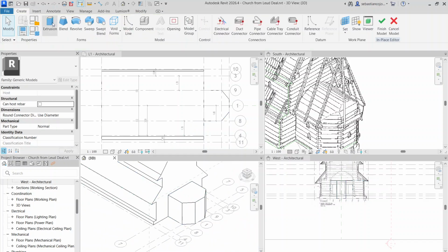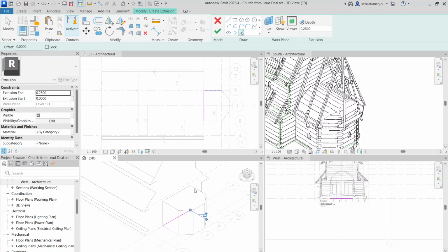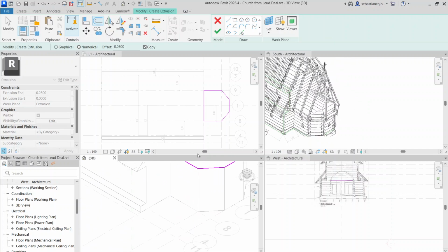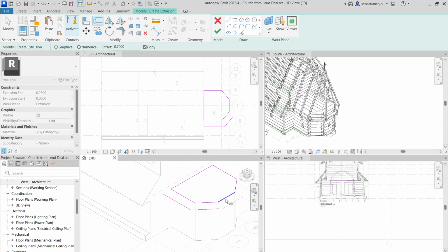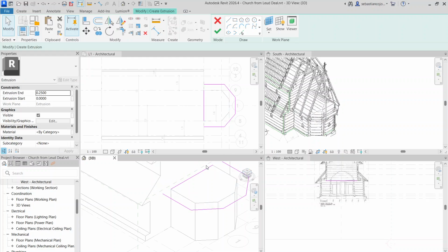And then on top of that, I'll create another extrusion, which uses this, that I should set a plane. This is the plane. I use these, but I will create an offset for all, or almost all, and that will be, let's say, 0.7. And that will make me a volume that is offsetted, of course, and then I'll cover some extrusions to cut off.